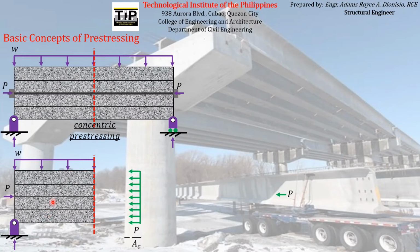And again, we know for a fact that this uniformly distributed load W produces internal force and moments at this particular cross-section of the concrete beam. And what are those internal force and internal moment? The internal force is a force acting along the cross-section. And that internal force, which is this, is what we call shear force V. That shear force is acting along this cross-section parallel to the cross-section.